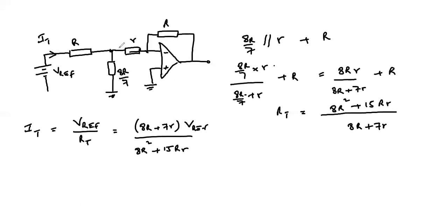The current that gets into the operational amplifier is the total current subdivided into 2 by the current divider theorem, as the current due to that resistor, which is the current contribution due to bit 3 that gets into the operational amplifier, which we're interested in.